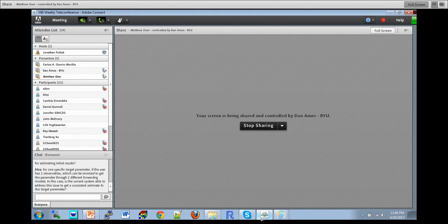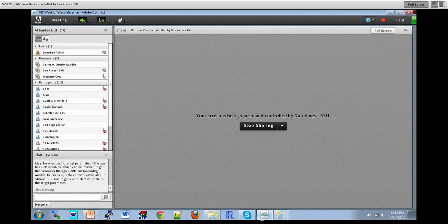Sure. There's quite a number. There's a family of pretty well-established methods, at least in hydrology, that are loosely based on optimization or Bayesian principles. Commonly, you've probably heard of maximum likelihood estimation. This is something that was done, I think, by Kitanidis and Dagan in the early 80s. That's much faster. There are also a variety of methods that don't infer the likelihood function, and that's where we incur the majority of our cost. If you assume to know the shape of the likelihood function, the cost of the process decreases considerably.